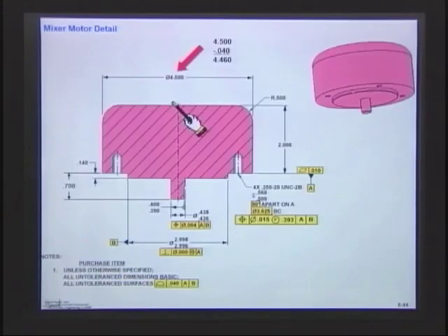And the minimum mount that we could have here, it says that diameter could be 4.500. That's the maximum it could be. But then remember, we had a profile tolerance of 40 thousandths, and when it's on a diameter, remember it's plus or minus 40, so the smallest that diameter could be would be 4.460, and that's this diameter here. Probably it'd be more appropriate if the dimension came on the bottom, but that's telling us that diameter.